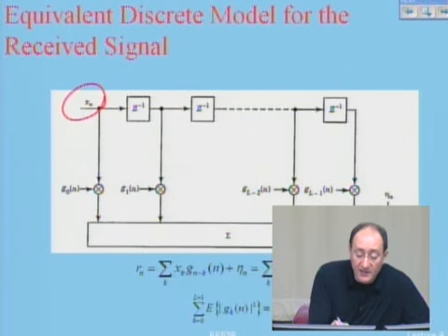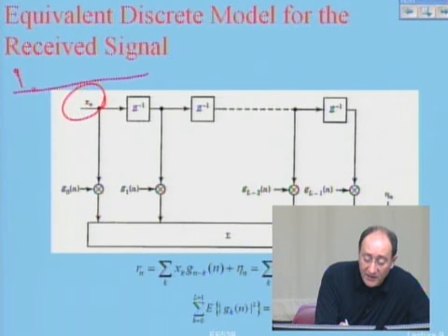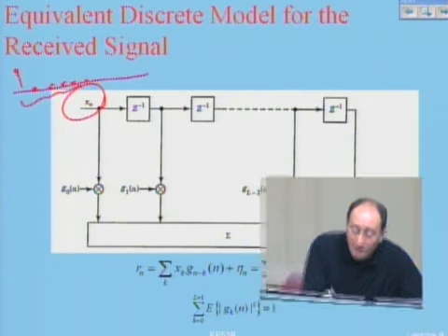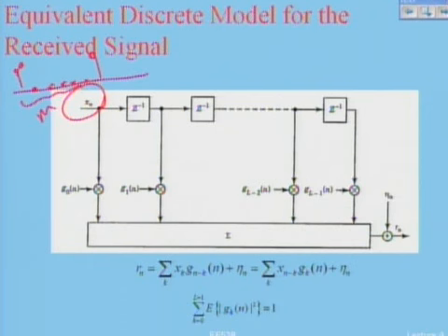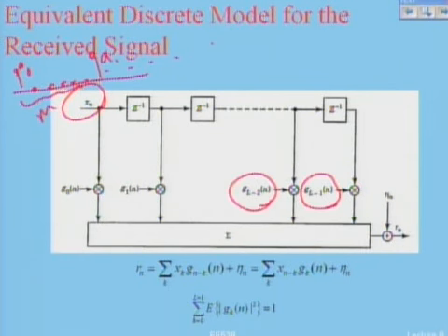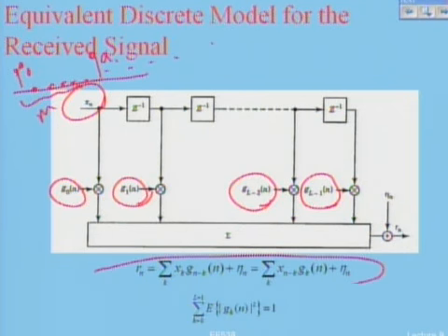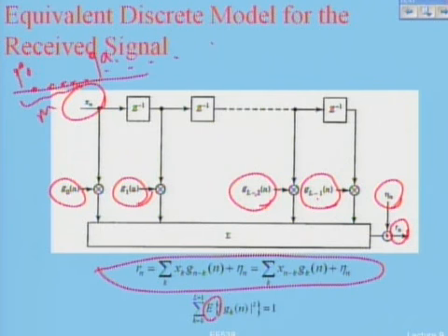These are the transmitted symbols. These are this thing, and then 0, 0, 0, 0, 0, m of them, and then this. This is A0, A1, and etc. It passes through a tap delay line. Each of these taps have a gain which is defined by this equation. And if I want to normalize, I get all of these tap gains, magnitude square, and I put it equal to 1. Average of that, or expectation of that. Okay? And then the output, I have some noise added to the output, plus R sub n. I mean, the output is R sub n.